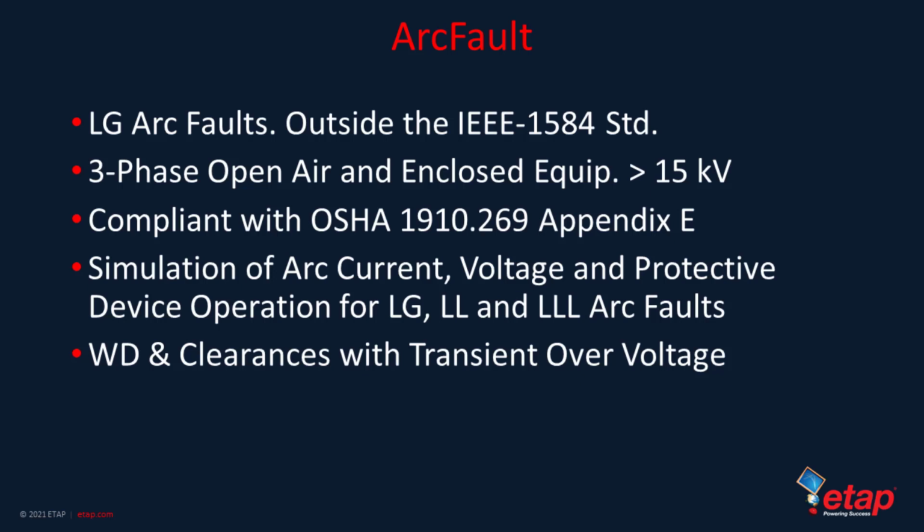Following protection and coordination is the ability to do arc flash, especially on some of these locations that are well above 15 kV, which falls outside the IEEE 1584.